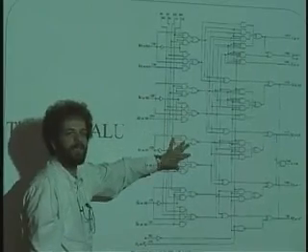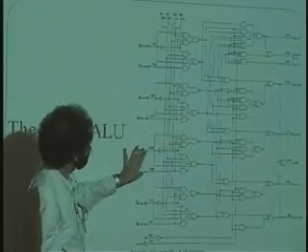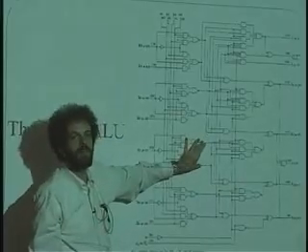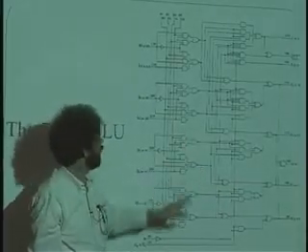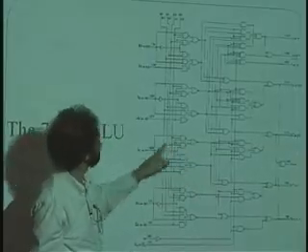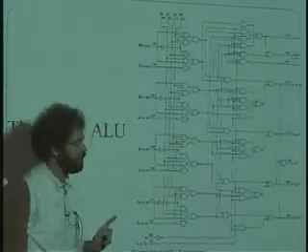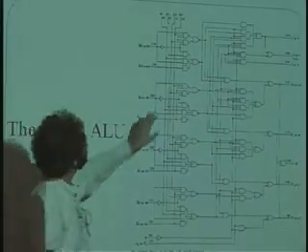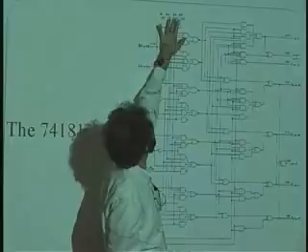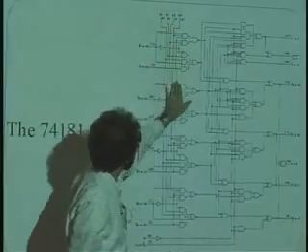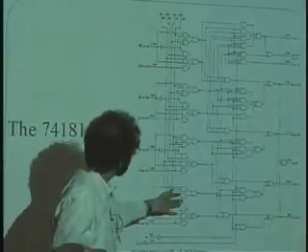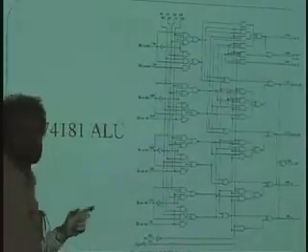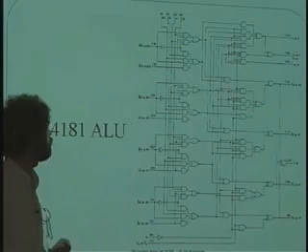Guess what the recoding is here between A sub 1, B sub 1, and the mystery wires right here. The mystery wires are G and P. Okay? And if you go through the logic here, what fools you a little bit is that this ALU doesn't only add. In fact, this ALU has 4 bits, S0, S1, S2, and S3, that go down all the way down here, and that plug into all these gates, and they allow it to do add, subtract, and or all kinds of fun things.